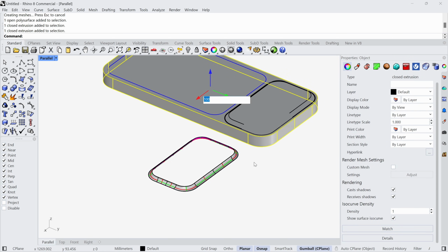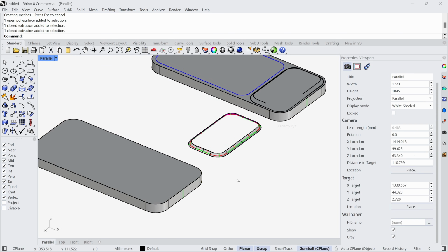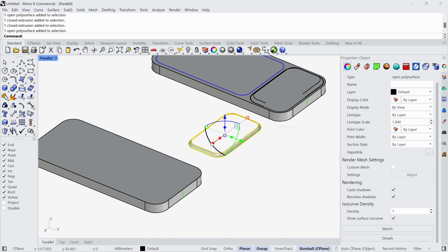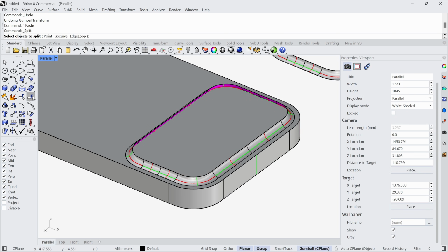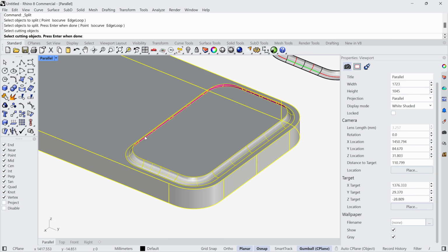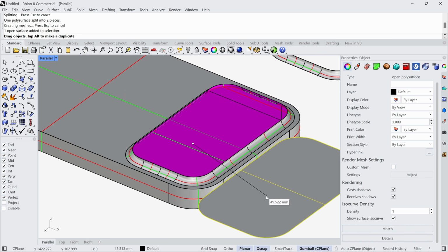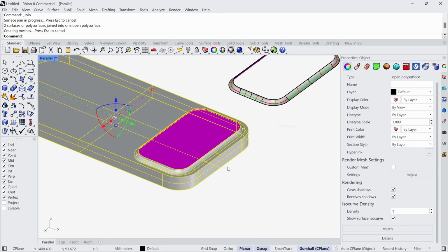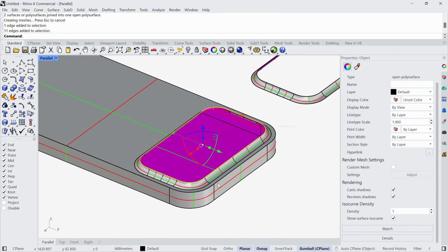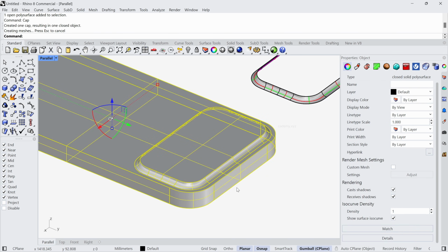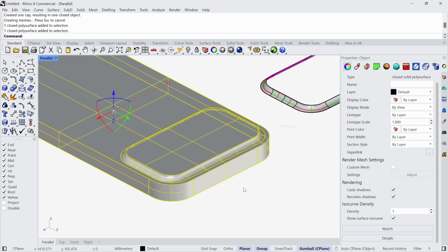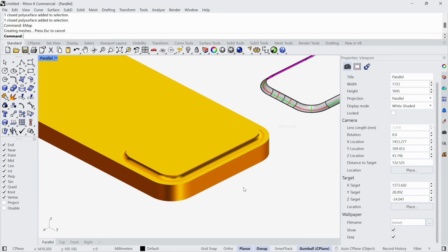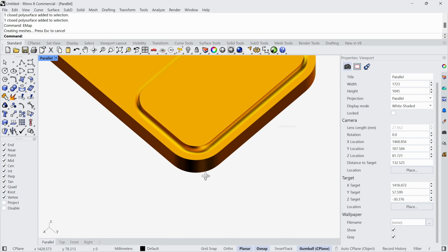Let me move it by 200 units. Let me move it by 100 units. I will split the solid geometry using this part. This is going to get rid of this small fraction of surface. We can now join everything together. And as this is a planar edge now, we can run the cap command, which is then going to fix this into a solid model. You can also check the quality by running the EMAP command. We have a high quality surface model.